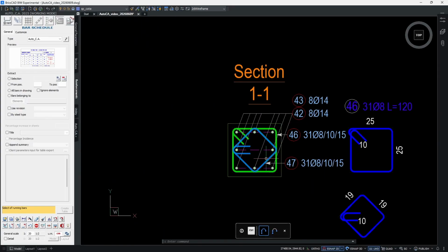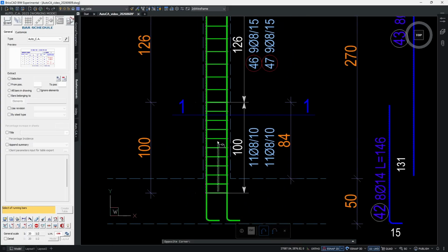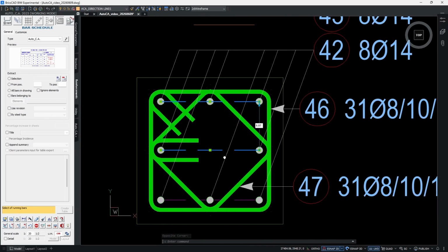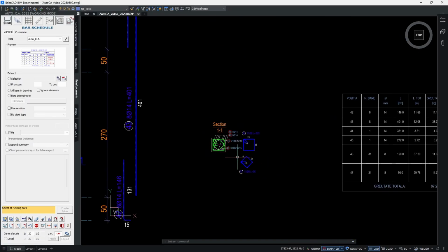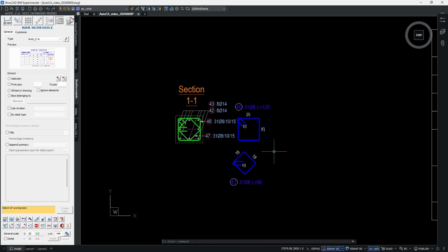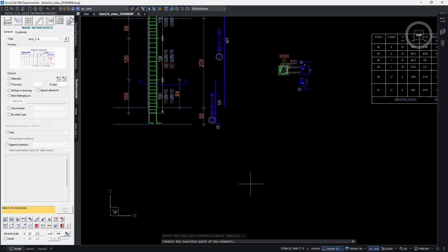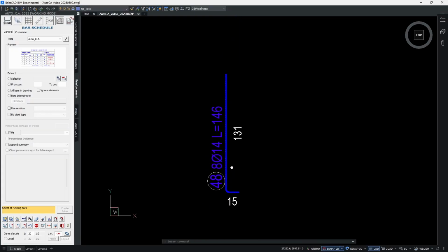The inside bar and the inside stirrup are often only for display purposes. However, the inside distributions, the bar series and the bar section series, are internal bars that increment the quantity of the outside bar if they are linked, as I said. Therefore, if you only copy the outside bar, like this one, you get a brand new bar that counts as one piece.